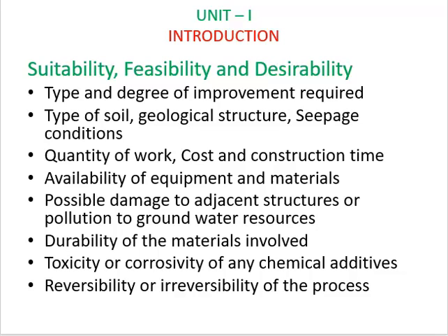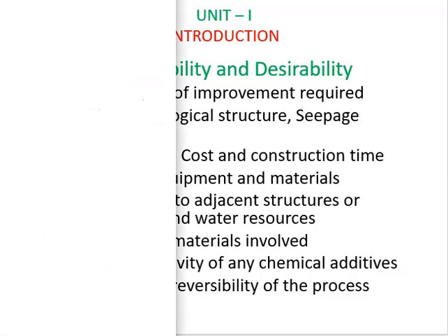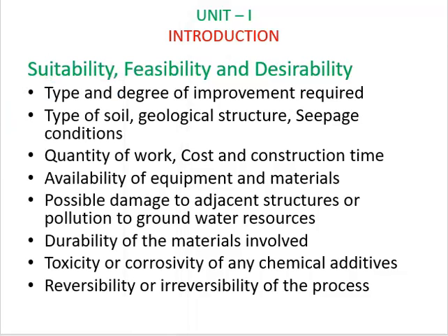Next point is toxicity or corrosivity of any chemical additives. The chemical agents selected for stabilization should not be toxic, should not react with the construction material, or should not corrode the foundation systems. Even the government regulations may restrict the use of few chemicals.